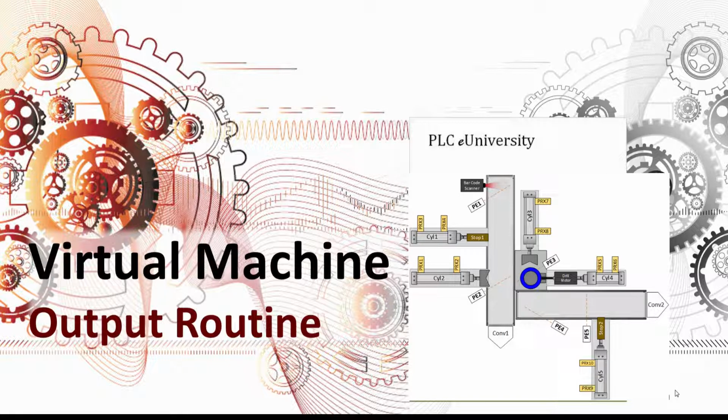But it makes it easier to troubleshoot because you go to one routine, you can find the output that you're looking for, and then work your way backwards with either search or with cross-reference to find the logic that's actually controlling that part of the sequence.